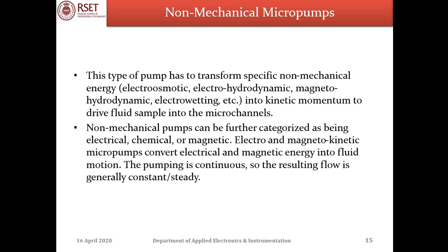They are used to pull ions into the pumping channel, in turn dragging along the bulk fluid by momentum transfer due to viscosity. So a few ions are actually pulled up with the help of the electric field, which results in the dragging of bulk fluid by momentum, which is due to viscosity. So this is what results in non-mechanical micropump actuations.